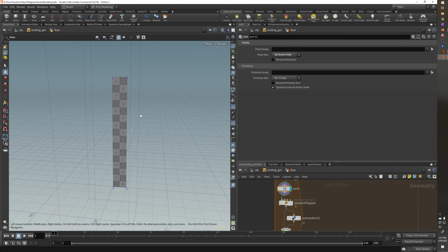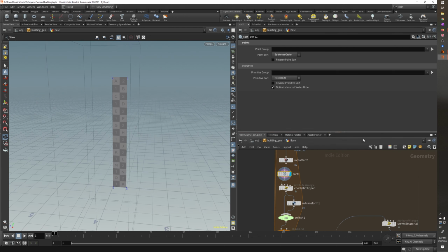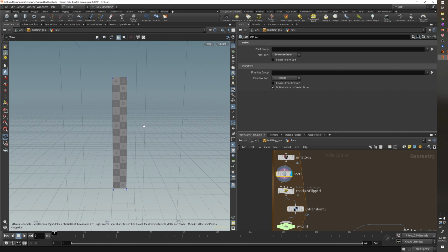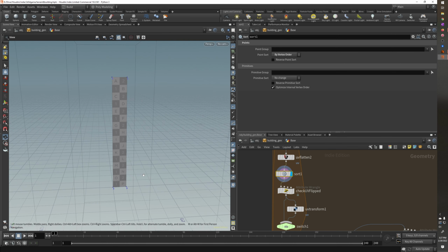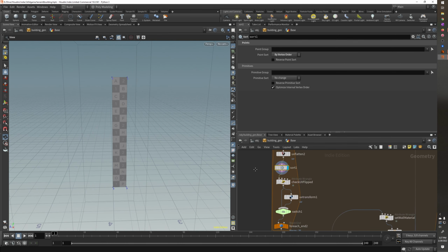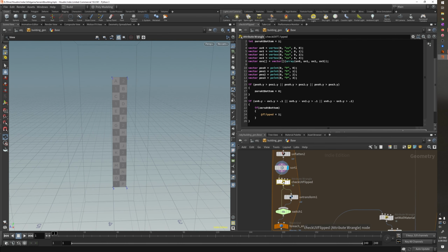This is awfully complicated, and it was annoying to figure out, but it's going to sound kind of simple. But so all of our points basically indicate the primitive order of our UVs. So we can have like a 1-to-1 if point 0 is basically going to be the same spot as vertex 0, and the vertices hold the UV information, which we're checking with the point information.